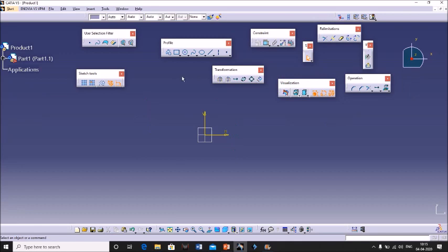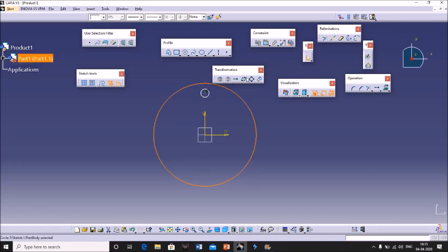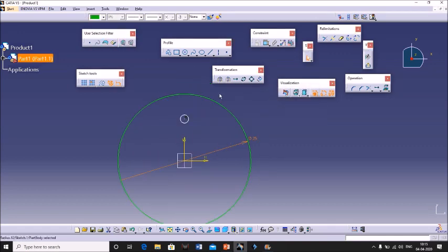In this we have some options in rotation and translate, I will explain about them. So draw a circle, and I have drawn another circle inside the circle. Given dimensions as 25 mm, and this small circle dimension as 2, and it is at a distance of 8 mm from the horizontal line. So I need to rotate this small circle around the circle at an angle of 360 degrees.